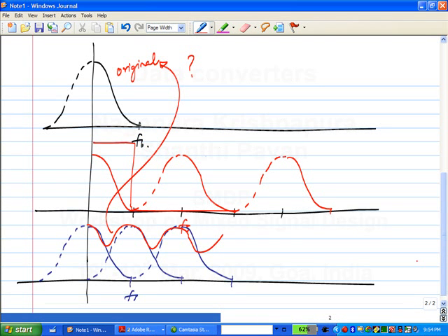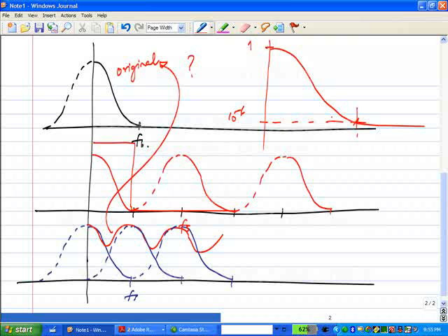Similarly, if the signal strength is below some value, so let's say, as you say, it will never go to 0. Okay? So let's say here it is 1. And here it is 10 to the minus 6. And after that it goes to below 10 to the minus 6. Now, you decide that you will neglect everything below 10 to the minus 6. So that's how, in practice, every signal is band limited. Okay? Although in reality it will never go to 0, you have to choose some point below which it is negligible. Now, what is negligible also depends on the application. In some cases it may be 10 to the minus 6, in some cases it may be 10 to the minus 2. Okay? So, we have different measures of bandwidth.